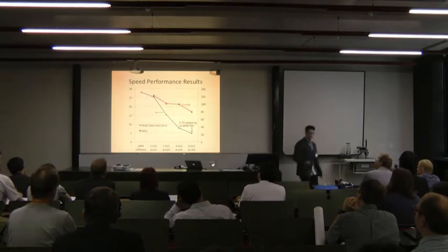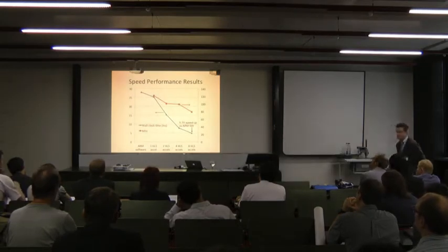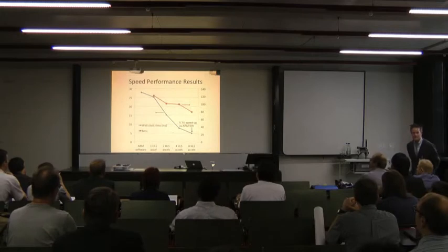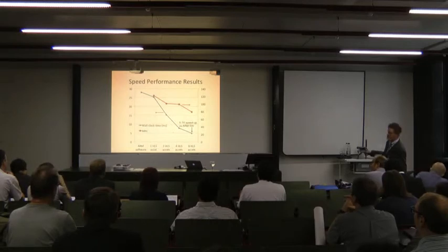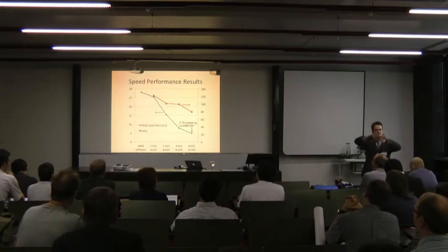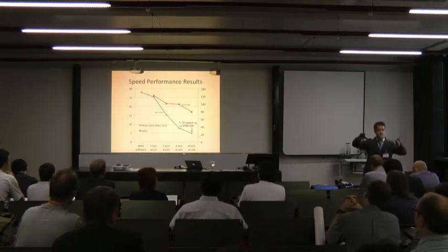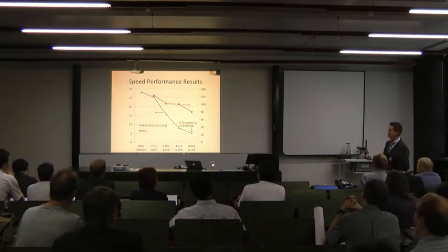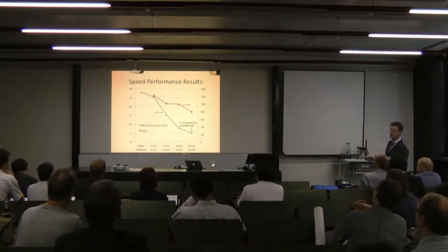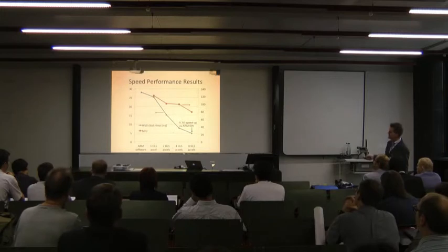Now, when we ran in the hybrid flow, where we have the ARM working with accelerators, we get these results. Here you see the ARM pure software, one LegUp accelerator, two LegUp accelerators, each working on different parts of the image. Remember, each pixel can be computed independently, so that's easy to do. 4 LegUp accelerators, 8 LegUp accelerators. You can see with 8 accelerators, you can actually get about a 5x, almost 6x speed up versus software.